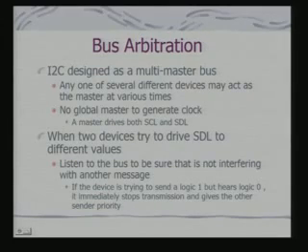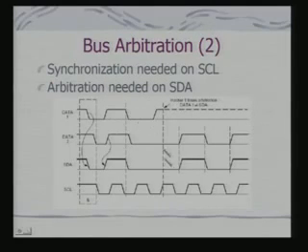The hardware should be built in such a way that when the device is withdrawing, it is not disturbing the data which is passing on the bus. And after some time, it should try again. This is the basic scheme of bus arbitration. If you look into it, this whole arbitration implies that there is a synchronization with respect to SCL, because all these decisions are being made with regard to your SCL and SDA lines.